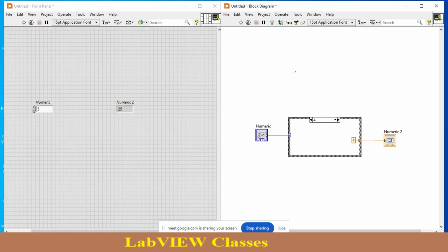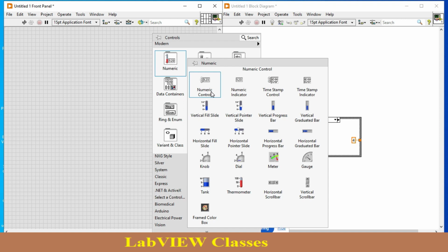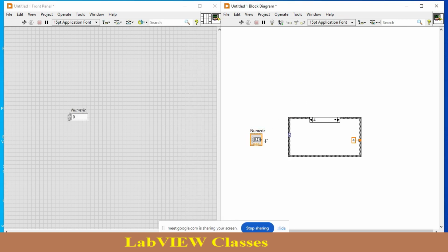So in the case of case structure, when you go with a numeric case structure, you just make a default also. Okay, so this is how you can go with case structure, and you can also generate a range. Like if I want to generate from 1 to 10 values, if I have a temperature, let's say I just make a case of temperature sensor, and in this case I just again create a numeric control over here.